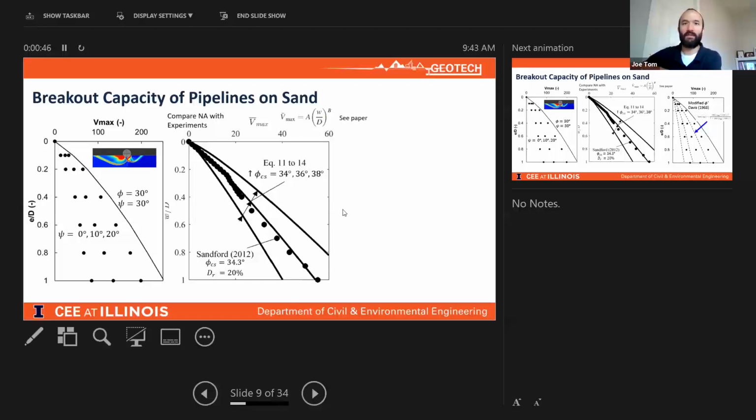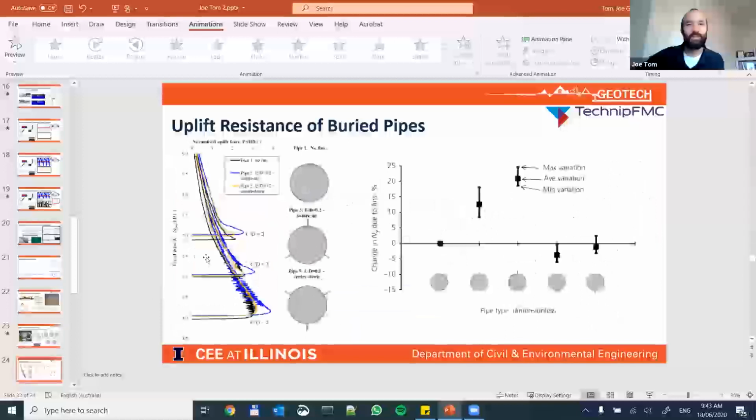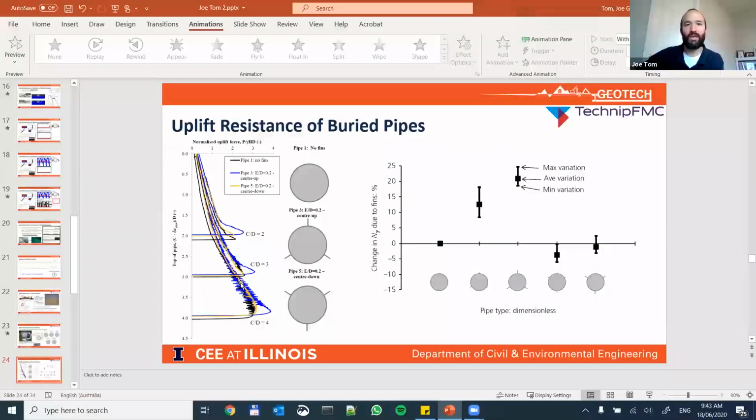The second, I was actually showing the wrong screen there. The second aspect is, as you displace, or as you shear something, there's strain-induced changes in the friction angle. So you get towards a critical state friction angle. And so your dilation is essentially changing during the process. This won't account for that.